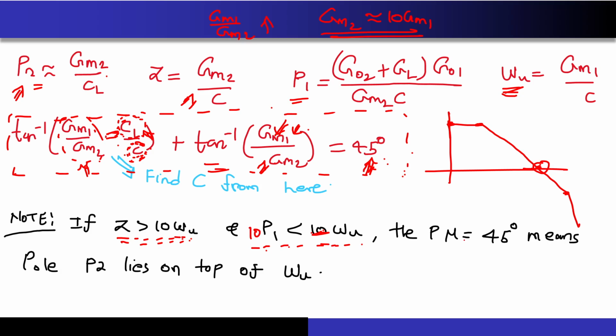Now the quantity that they have mentioned is that you are getting a phase margin of 45 degree. Remember this: whatever phase degradation this pole had to cause, it has already caused by contributing a 90-degree phase at omega UGB, because it cannot contribute more phase than this. This is the maximum that a pole can contribute. The other terms that can degrade the phase margin are nothing but these two, the pole and the zero that you have.